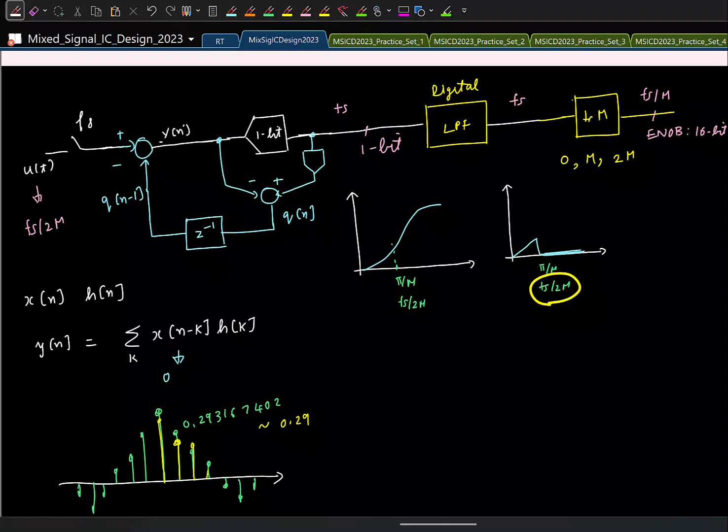Okay. So, ideally let us say the frequency response looks like this. So, this is pi by M. Within this band it allows everything completely and then filters it out. Now, I will not be able to represent this with infinite precision. I use a very small number of bits to represent. So what can happen is this, the filter's frequency response can get distorted, right? So if this happens, I will not be able to reject this fully.